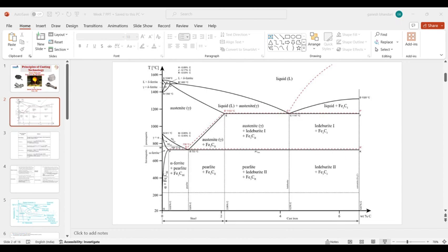The coarse structure produced during solidification breaks down to a much smaller size. Machinability and ductility increase because we are talking about grain refinement, so grains will be of a much lower size. Hardness will be reduced, and all structural imperfections get removed. Then coming to the next one,